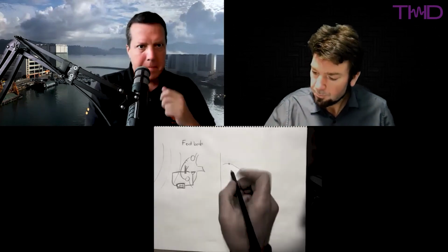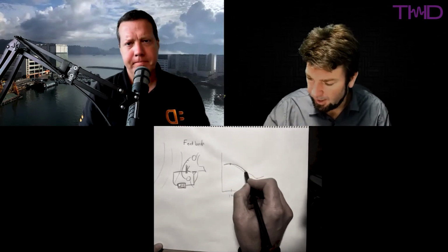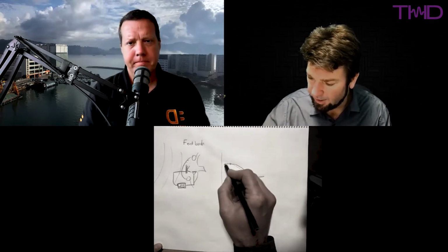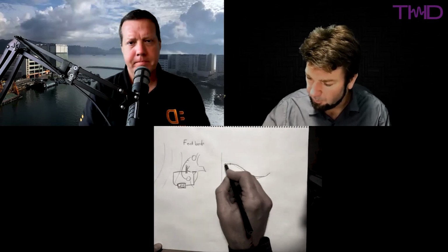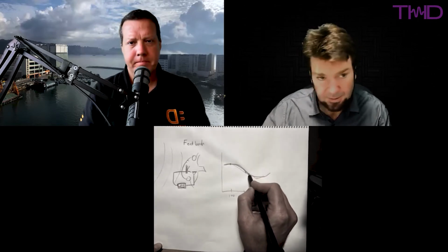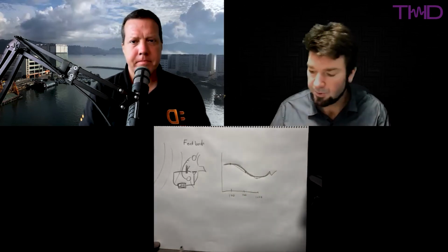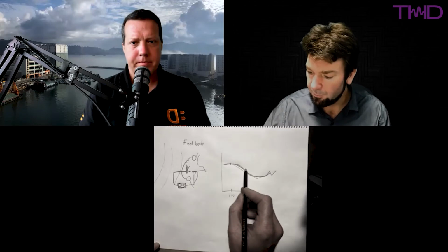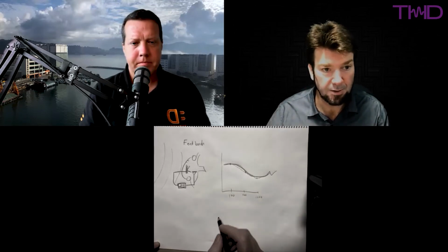So I drew sort of a semi-curve here. You often end up with something like this in a headphone. I'll draw it a bit more idealized. Low frequency is fairly even, and then the level drops down in the mid-range, and maybe you have some bumps at high frequency. And when your magnitude looks like that, your phase has more or less the same characteristic.